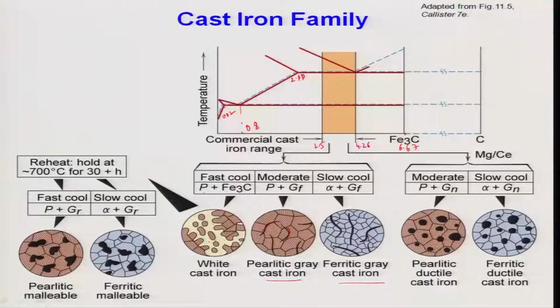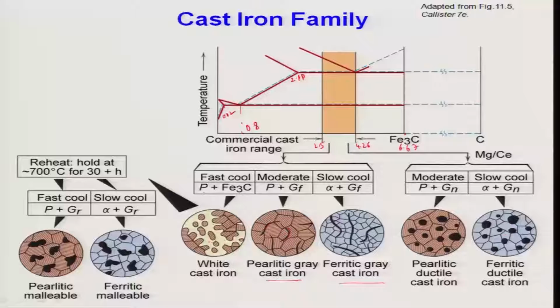Why? Graphite will absorb all the carbon, but basically you are adding this magnesium or cerium, then only you can change the shape from flake to nodular. That is the idea. Without that, you cannot basically do that. So, the addition of magnesium, cerium, lanthanum or calcium is basically due to what? Due to the shape change. So, thus this is for the solid state, liquid to solid state, from the liquid where the eutectic reaction happens. Now, there is another part of the story.